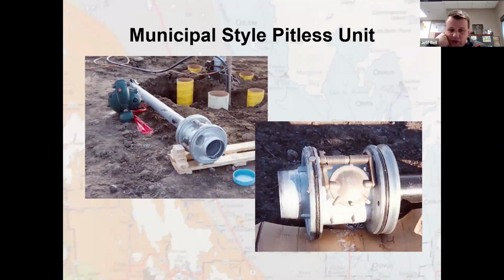One section that we often see with water wells that tends to be a real problem is you can't completely seal a water well. You have to allow the well to vent. It's basically if you would take a pop bottle, for example, and stick a straw in it and then seal the straw into it and you try to suck the fluid out, the pop bottle will collapse in on itself because you need air to take the space that you've taken the water out. And it's the same principle with a water well.